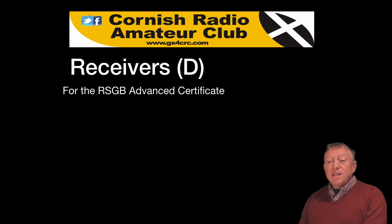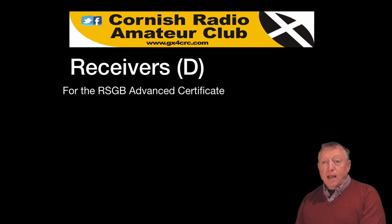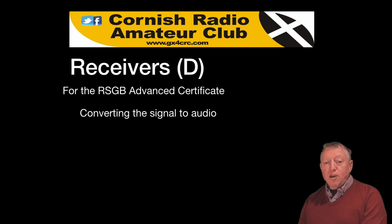And here in Receivers D, we're going to have a bit more of an in-depth look into some more aspects of superhet receivers, including IF amplifiers and AGC, but with a particular emphasis on demodulation.